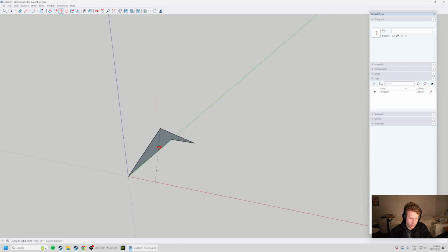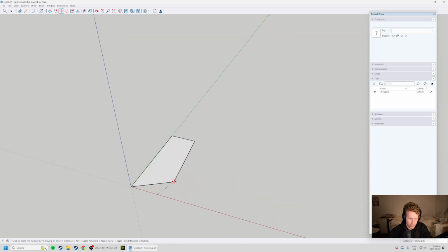So this is also a good thing to remember, that two-dimensional objects that are drawn in a plane, you can't adjust their vertices, because you can imagine in 3D what this would look like trying to fold up a single point. We'd have a lot of triangulation within this geometry, and SketchUp just isn't, I don't want to say it's not smart enough. You can do tessellations and triangulations, but for now, if you're just trying to drag out a point, it's likely just going to be happening in plan. So red axis, green axis, 2 dimensions, and that should be good.